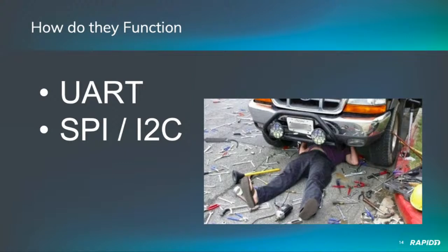With SPI and I2C, they're actually synchronous, meaning there is a clock that's determining the communication timing. For instance, SPI operates on a slave master model. The master determines the clock speed. That's the one with the actual crystal that determines how quickly data is going to be sent. The slave is going to basically accept that at that particular rate, and that number is negotiated throughout the process. I2C functions in a very similar way.